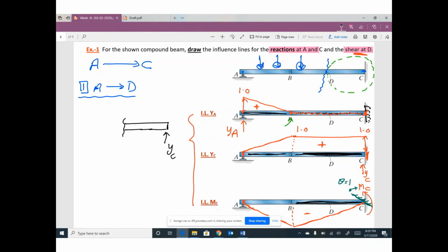At this location, we have moment MC. And also, at your cut, we have shear. Would like to rotate this member clockwise, so I will assume it like this. This point is D, so this shear will be VD. And we have moment, would like to make this member to smile, MD.